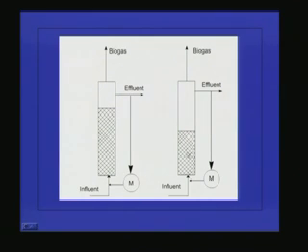The advantage of the expanded bed reactor compared to the fluidized bed reactor is that here the recirculation is less, because we want to expand it only 30%, so the velocity will be less compared to the fluidized reactor. So the pumping cost can be reduced in the expanded bed reactor, but efficiency-wise, the expanded bed reactor efficiency will be lower than the fluidized bed reactor, because in the fluidized bed you will be getting more contact between the biomass and the organic matter in the wastewater.